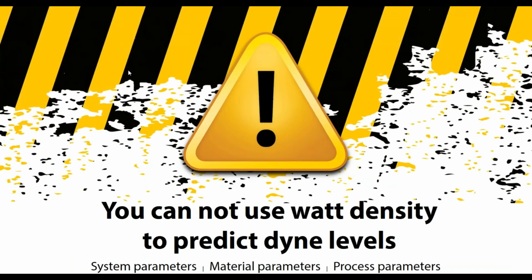Finally, in this part of the presentation, one cautionary note. You cannot use watt density to predict the dyne number. You're probably thinking, well, I wonder why that is. Why don't these things just march linearly with each other? So if on one polypropylene film I get a watt density of 2 and get 40 dynes, and I run another polypropylene film at the same watt density, I don't get 40 dynes, I get something else. And why is that? We must have to blame the corona treater for that. Well, maybe and maybe not, but we'll get into this as we go forward. But please remember, you can't use watt density to try to predict dyne numbers.